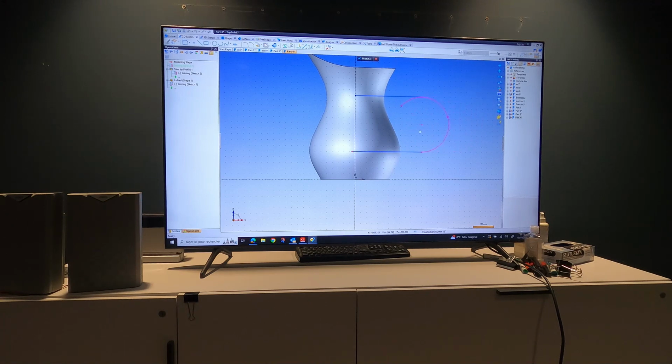Okay, and also look, you can trim this. So now we're getting back to that. Trim it. Okay. So now put the correct constraint. Close this, trim, and you have to put the distance constraint from this here to this. Here. Now it's gotta be 45.